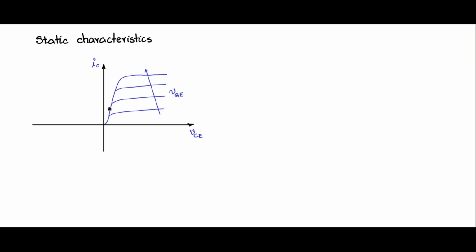This region is the on state. So less than this region, where VCE is less than this ohmic drop or the saturation region, we call it as the on state. In the IGBT, there is an extra added part, which is the reverse part of the characteristic.